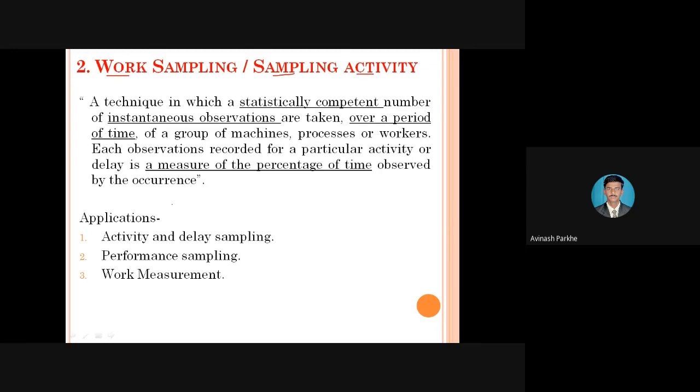But for the 5 samples you have selected for measurement, if you get different results, maybe sample number 1 has different dimensions, sample 2 different dimensions, sample 3 different dimensions. If in all the samples you get different readings, at that time the total 100 products will be rejected. So such types of sampling activities are performed in production departments for acceptance and rejection purposes. The same concept is somewhat implemented here in work sampling.